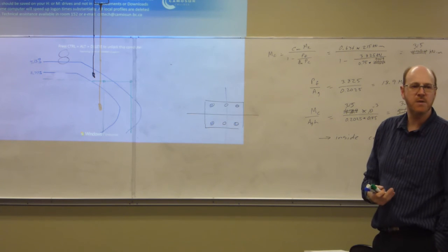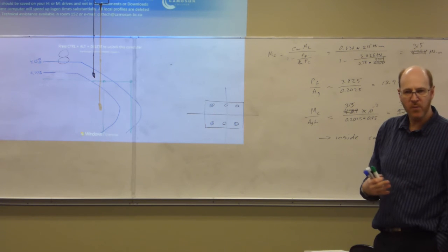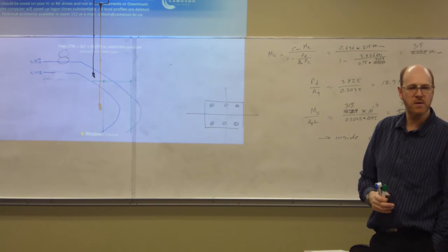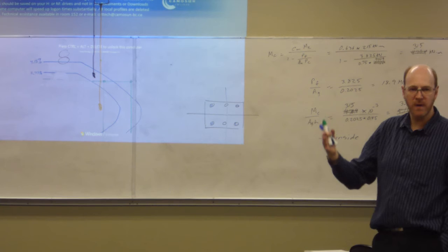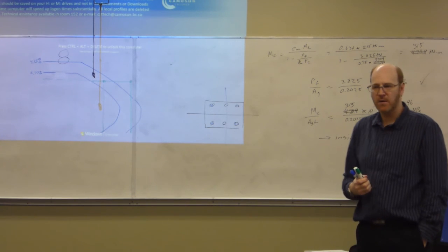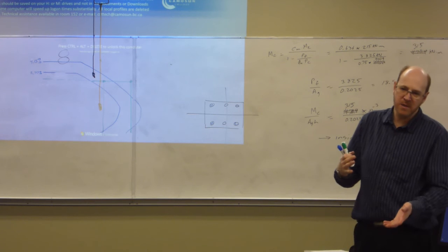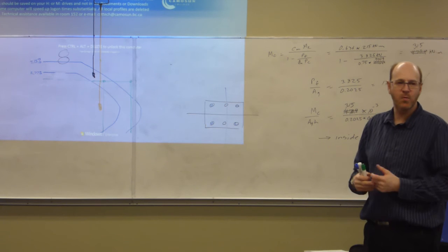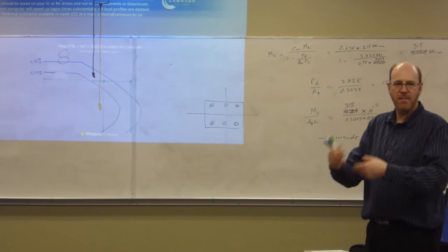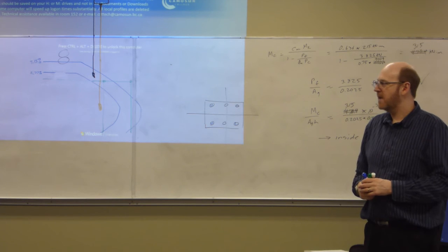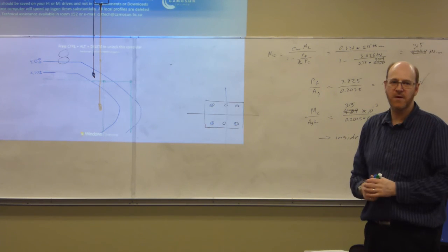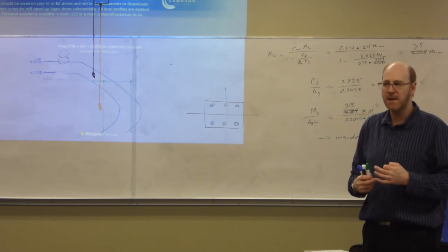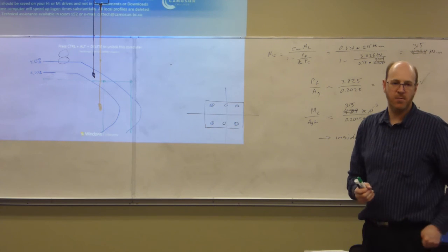But of course, in most engineering budgets, we don't have that much money. So you're going to come up with a quick and dirty calculation, figure out your maximum moments, maybe do a little bit of reduction in areas where there's low moment, come up with a pattern that works, and once you've got something that works, you're happy with it. Right? We're not necessarily going to go, okay, well, I know my most optimal configuration is with rho being about half of rho balanced, so let's go back and redesign the beam, right? Come up with a different width and height, come up with a different strength of concrete. I mean, we could interpolate and iterate over and over and over to come up with an optimal configuration. And in most cases, we're just going to do one quick and dirty, get it right the first time. And so right meaning that it works, and then we move on and do the next part.